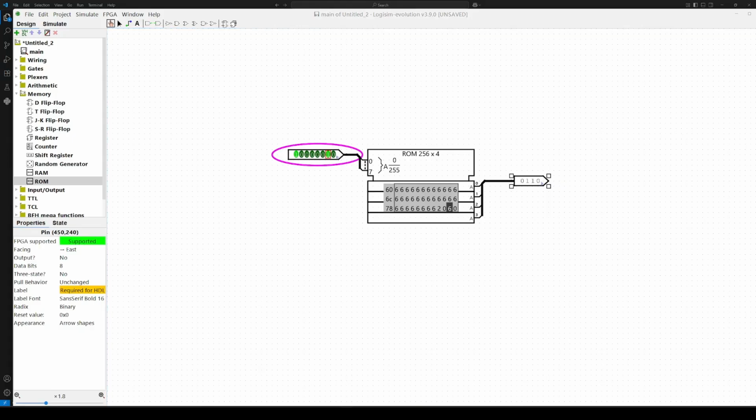All right, everybody. So that wraps up our deep dive into the ALU Control Unit. If you think about it, we started this video with the theory behind how MIPS instruction types guide ALU operation. Then we moved to our gate-level implementation, and I also showed you how to program the microchips using the ROM for full control signal decoding. If you followed along, congratulations, you just built a crucial part of a working MIPS CPU.